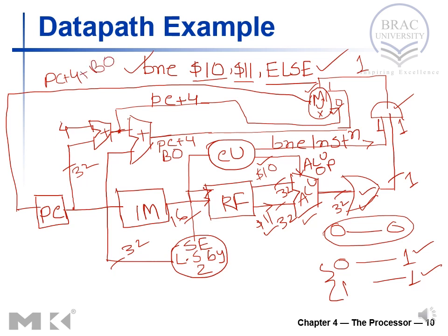This is how the branch target address is calculated, and this data path executes branch equal to, and at the same time, if it is required, then it can execute sequential instruction at the same time. If it is not equal to, that means the execution is sequential execution.